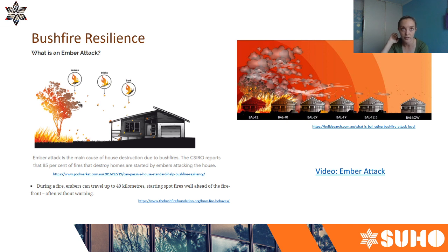Embers can travel up to, I think I read, 40 meters or more. If an ember lands in your windowsill, gets under it somehow and starts to smolder, and then your curtains catch on fire, that's a very significant risk during bushfire. So if you've got an airtight structure, you're not going to get embers inside your window frames.